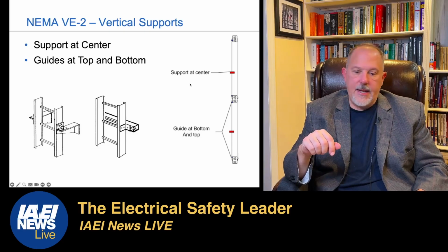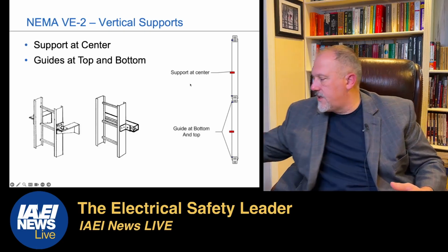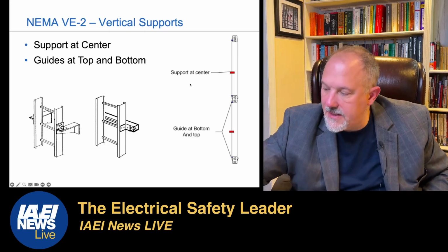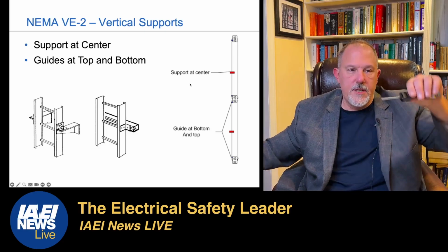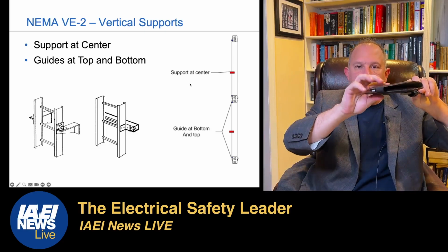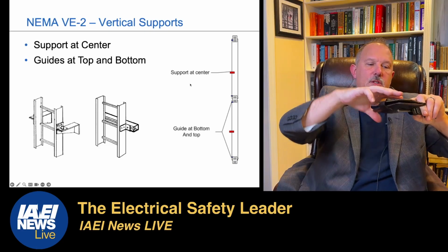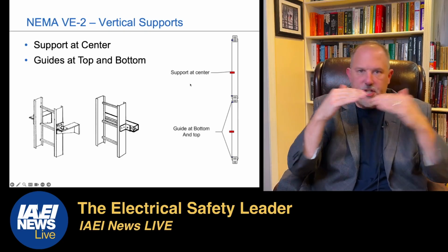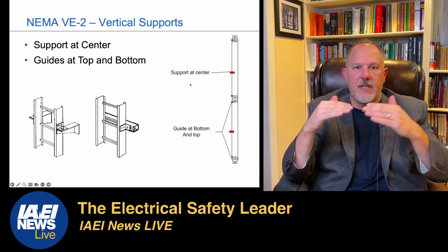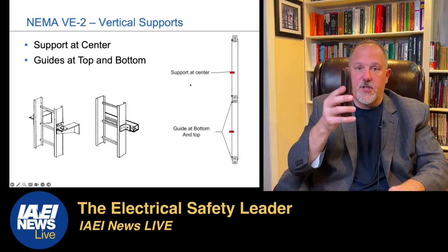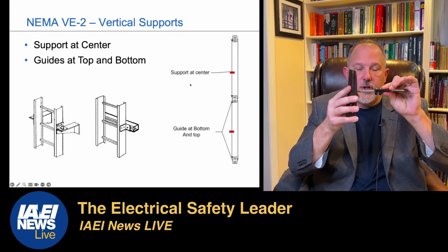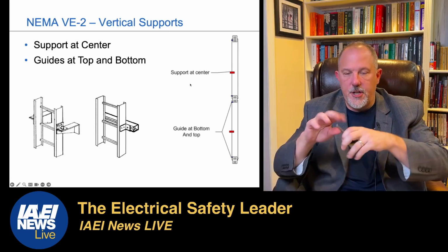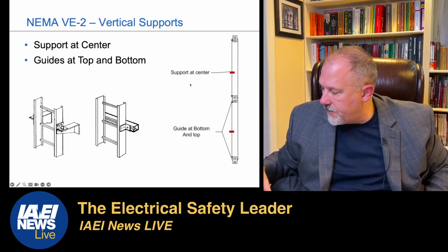cable tray sitting on a truss. Let's say that this is my support and it's horizontal and my cable tray sits on top of that. My bolts that are in there are not necessarily experiencing the shear. They're experiencing some, but if I'm supporting it this way and I'm securing it this way and I'm relying on this bolt, now the shear of the bolt is what is probably my weak point.